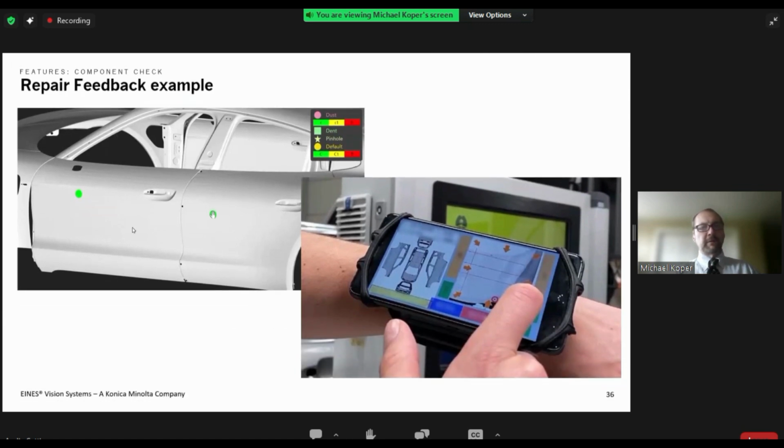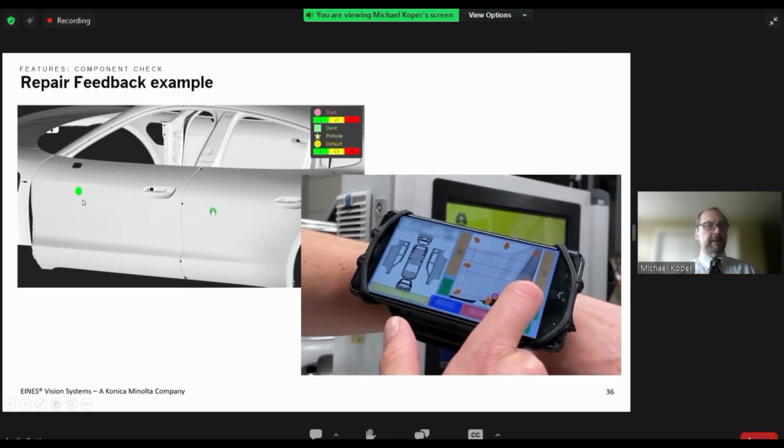The feedback is super important on the paint defect detection systems, not only as to placement on the vehicle and location of the vehicle, but it needs to be bought off. So you've got to have a device where we do display these on overhead monitors, but we're very agnostic to any type of tablet or smartphone that we can put the information on, and an operator can quickly say, oh, there was a fault on the door. It's up in the top region.